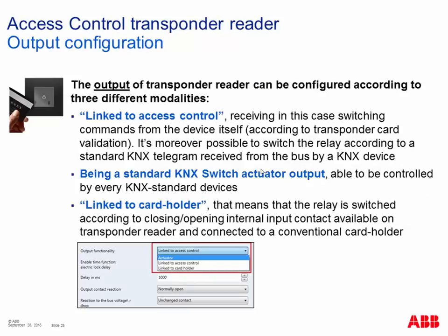The ETS programming is very simple. Remember, it's a KNX device, so via ETS you can program the device freely. The ETS file is very simple, and the most important configuration is the output configuration. Remember, the device has one output, and this output can be configured in 3 different ways. I show you now which are these 3 different ways.